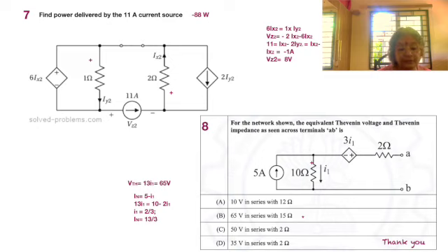So that's first to be understood. Then we move on to the voltage balance. The voltage drop across AB is 0 because it's shorted, and we have a voltage across the 10 ohm resistor given by 10 I1. We also have 3 I1. So 10 I1 plus 3 I1, which is 13 I1, is equal to the voltage drop across the 2 ohm resistor, which is IN times 2, that is (5 minus I1) into 2 ohms.